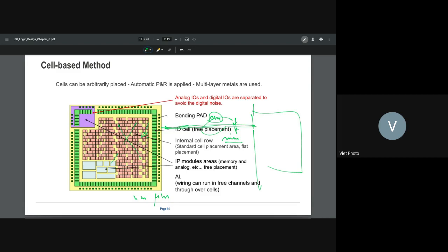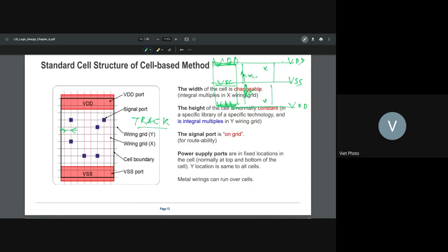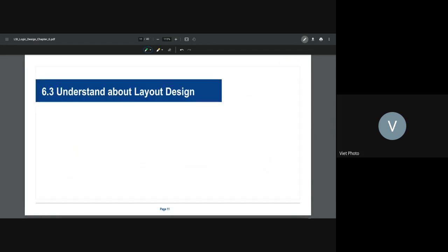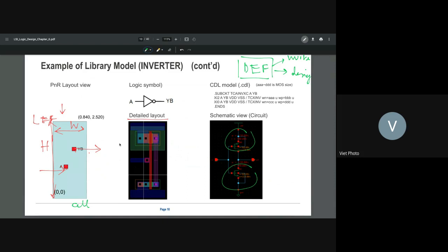So when we have it, usually it will be opened up. For example, let me go back to this one. You see that this cell is in symbol 1. This one is the poly that I talked about, and this one is a middle one, for example. The middle one is connected between the P transistor here and the N transistor here. It connects here, right? That is the connection in the middle. But you see that the middle one is used from here to here only, so all the space left here is kind of empty.